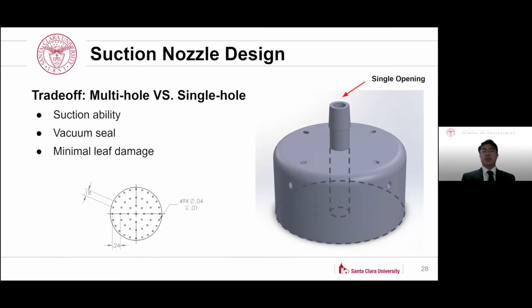The various gripper iterations were 3D printed out of PLA for this purpose. However, TPU or silicone would be other interesting materials to work with based on their flexibility. And overall, we'll see that the single hole proved better functionally in simulations and testing.